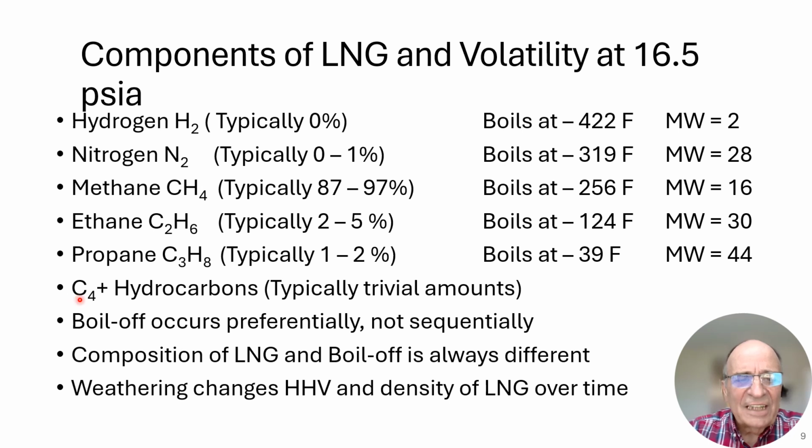Typically, LNG does not have very much C4 plus hydrocarbons. Typically, you'll find trace amounts of butane, pentane, hexane, and hexane would be very, very little, and anything higher hydrocarbons would be too. You'll never remove every molecule, but there'll be only trace amounts.